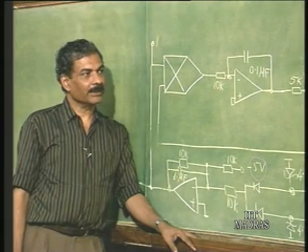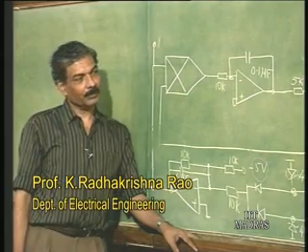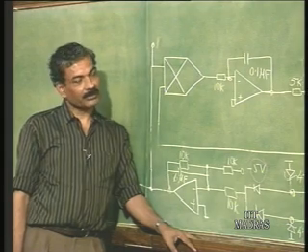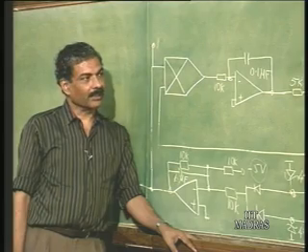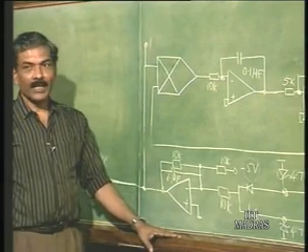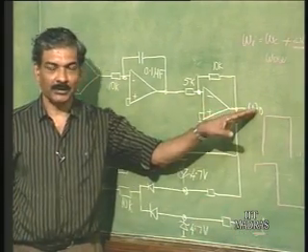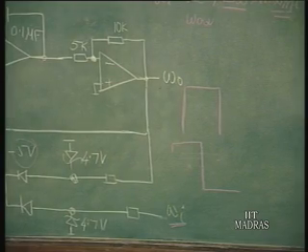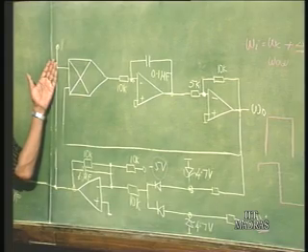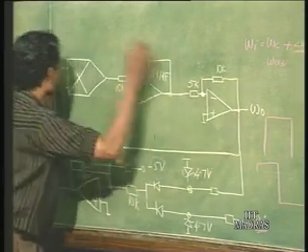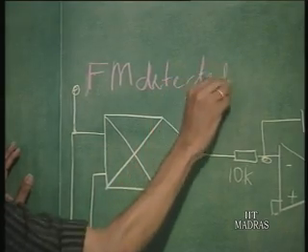In the earlier demonstration, you had seen the signal conditioning effect of the phase lock loop, where FM at the input produces FM at the output, FSK at the input will produce FSK at the output, okay, of higher signal strength, better signal to noise ratio, etc. Now, its application as an FM detector you will see. Obviously, if FM is inputted, FM is outputted at the output of the VCO. Now, what is going to be the modulating frequency? That is straight away coming at the input of the VCO. So, if FM is produced at the output, this is going to be the FM detected output.